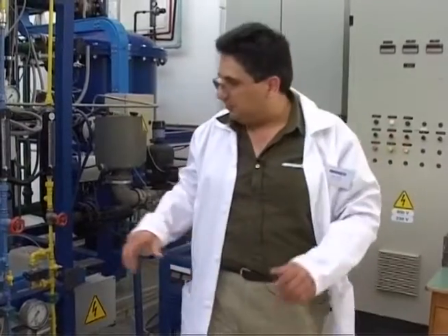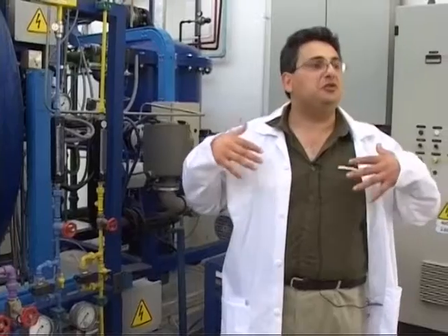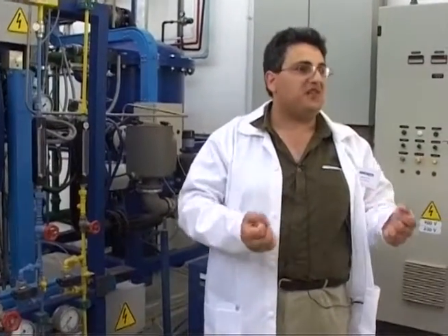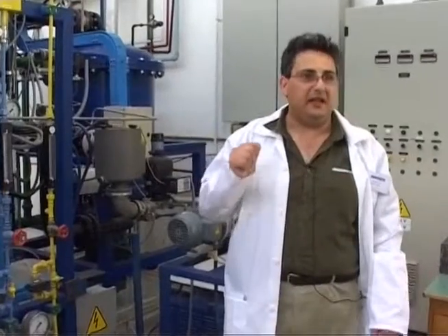The temperature is afterwards increased, keeping the concentration of ammonia constant, allowing nitrogen to diffuse inside the material, creating a diffusion zone which supports the high wear-resistant surface of the component. It is important to create a deep diffusion zone because it is useless to have a very hard surface without a tough and supportive layer underneath. Otherwise, the surface will crack and chip off.